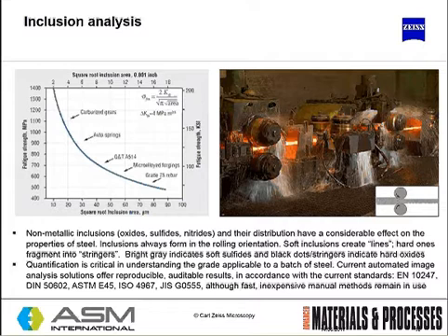You're able to do some qualitative analysis of these surfaces. Bright grey will typically indicate a soft sulfide, but black dots in or outside stringers indicate that there are hard oxide inclusions. Graphite analysis is also possible within specific modes in a typical analytical light microscope as well. So even with a light microscope, you're able to provide some qualitative information about the chemistry, and quantitative information about the grade applicable to the batch of steel according to the number of inclusions.